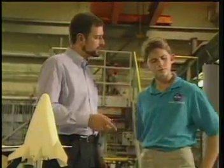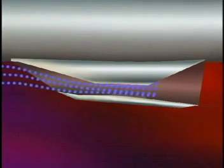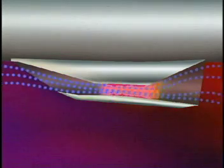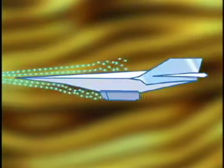However, for the HyperX geometry, we require turbulent flow. Why would you want turbulent flow on the HyperX? In order for the scramjet engine to work properly. You see, turbulent airflow enhances the mixing of the air with the hydrogen fuel for better engine performance. Turbulent airflow is created by a device called a trip located underneath the belly of the HyperX.